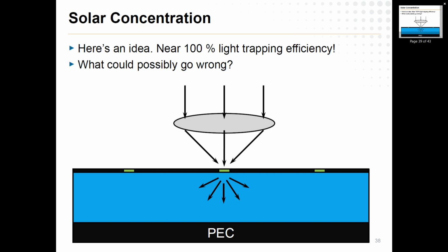Ones need to track the sun. Yes. What if the sun is not right here, but over here slightly? What will happen then? All the light will bounce off of here and never touch my cell. So now I have to track the sun. Whereas before, it didn't really matter which direction the light was coming from. I didn't have to perfectly align everything. Now I have to point at the sun. So now I need tracking, which is big and clunky and expensive. And I've got this giant heavy thing in front that has to be dealt with. So that might add a little bit of cost.